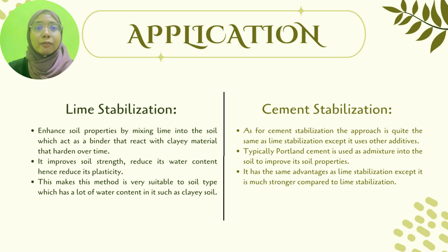From the aspect of immediate compaction, it offers better distribution, higher strength at a higher dosage, and better performance in certain soil types, such as coarse grain soil, where it can provide significant strength gains. In contrast, lime stabilization may be suitable for higher plasticity index clay soils.